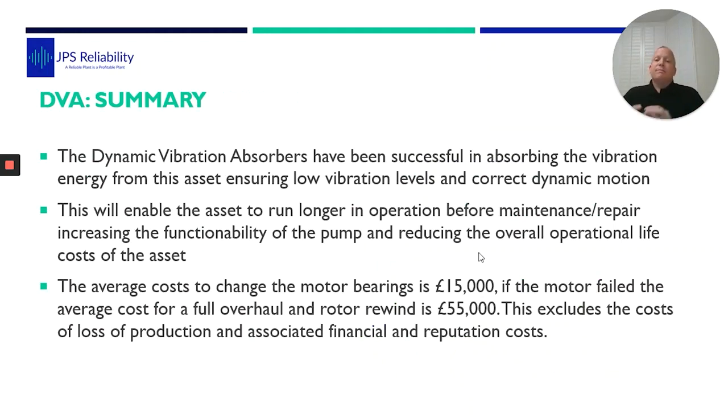So the summary is, you may think DVAs are a patch, a temporary fix, but you need to look at every single job. You need to stand back and look at it, because yes, we would have liked to rip down a pumping station and build a new pumping station. Pumps were all great, never had a problem. But in this instance, the pumping station was so old, it cost too much, and would disrupt production, the process, the customers. You just can't do it. So this was the only realistic opportunity to make the assets last longer.